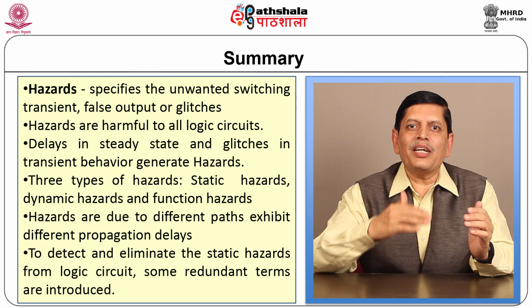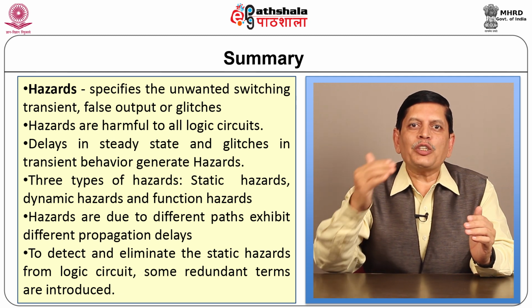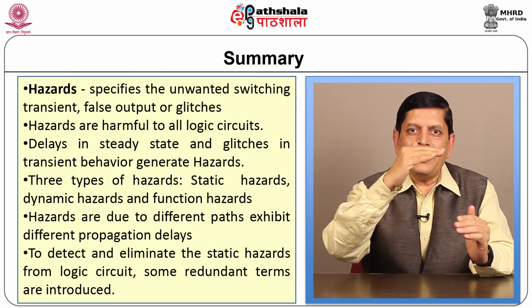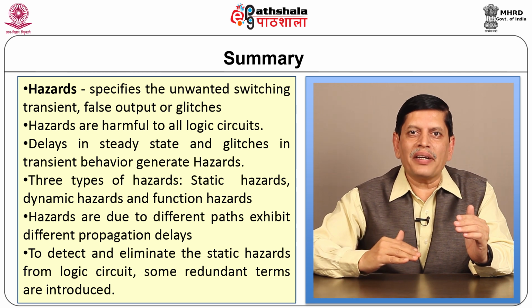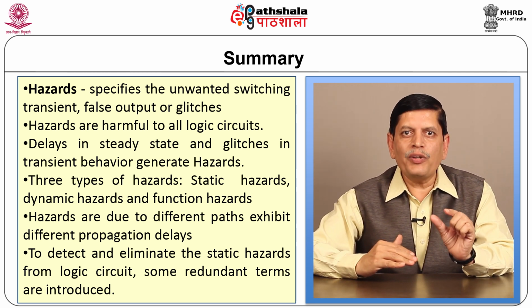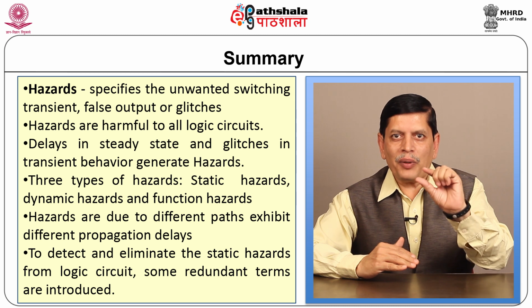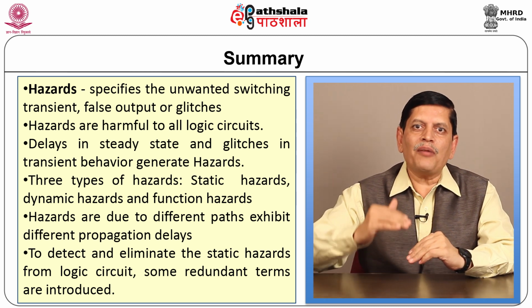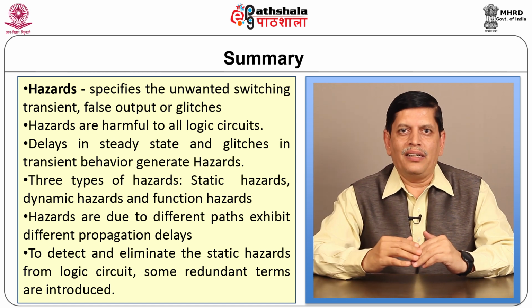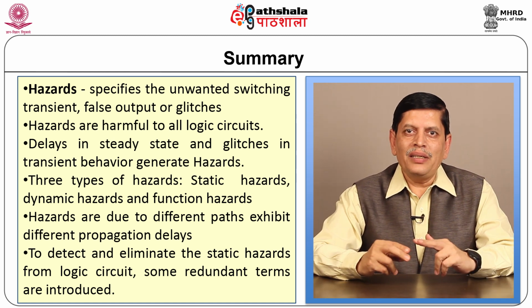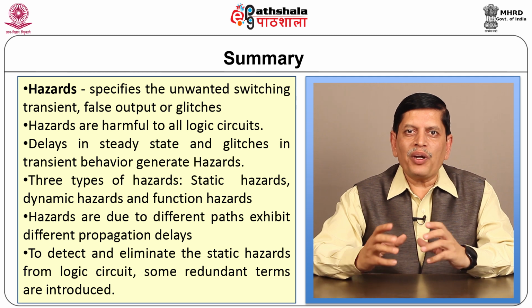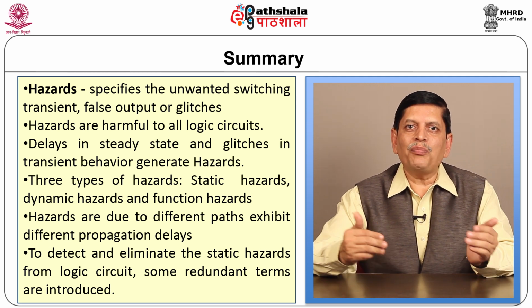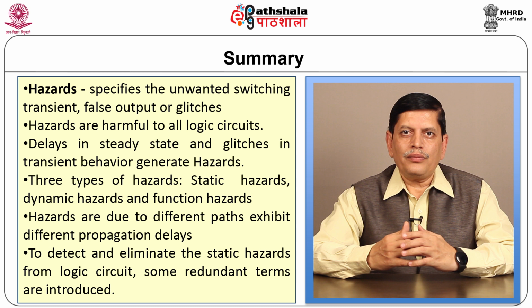Similarly, in case of static 1 hazard, the output is expected to be at high state, but it goes low temporarily or momentarily for a certain duration, which is proportional to the propagation delay of the logic gate, and then it will come back after some time to the desired state. So, in both the cases, these are unwanted propagation delays which are affecting the performance of the circuit.